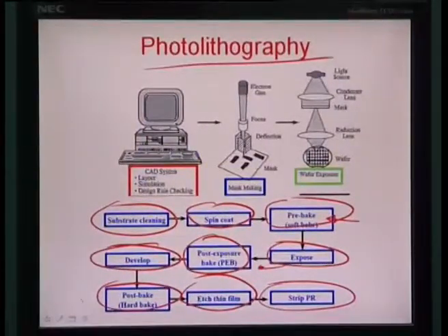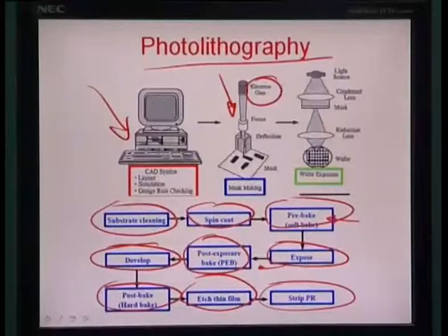Some of these equipments are used typically for lithography. You have a CAD based layout planning, simulation and designing center, which, using a laser beam or an electron beam, writes on the masking material. Soft masks are made using black and white transparencies of a certain resolution, but hard masks, which are used for better, high resolution feature sizes in most of the industries, are made by a coating of chrome over a glass surface, which is laser etched or electron beam etched, and very precise features are machined onto that thin layer of chrome.